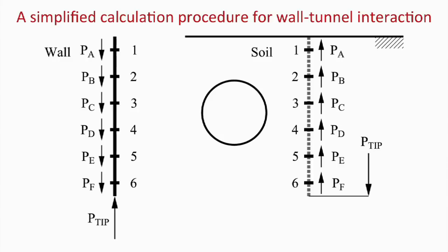Again, you have to, for instance, in the vertical direction, make equal the displacements in the vertical direction. But in the second case, on top of the forces acting in this particular position, in which you have the discretized wall, you have the tunnel. And therefore, any displacements induced by the tunnel have to be introduced here now, the vertical ones. And of course, you have to ensure all the time equilibrium, okay? Total equilibrium.